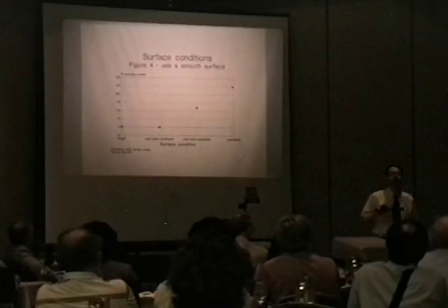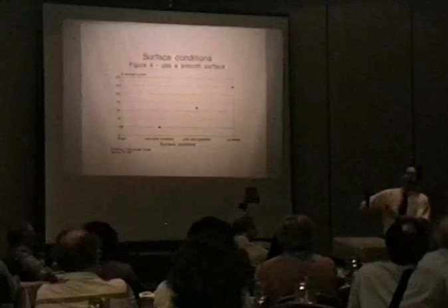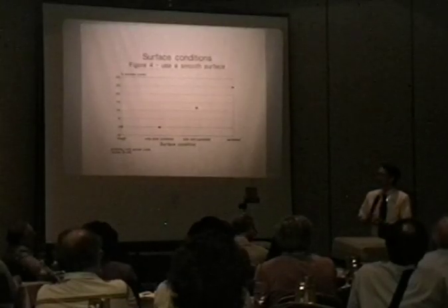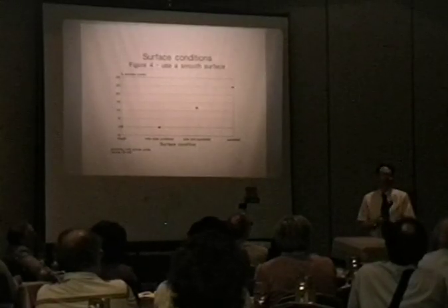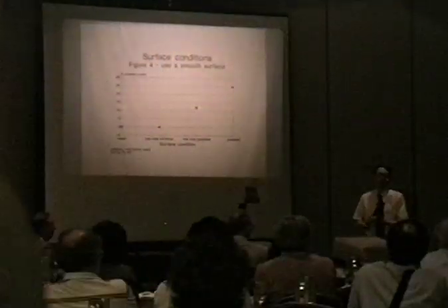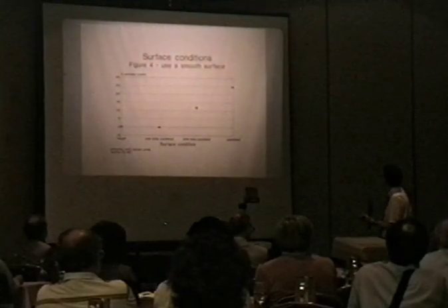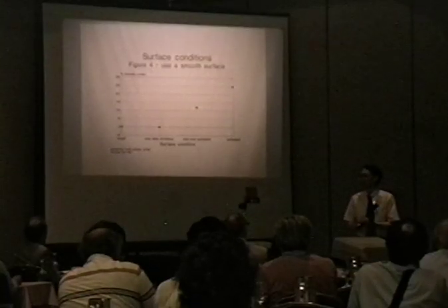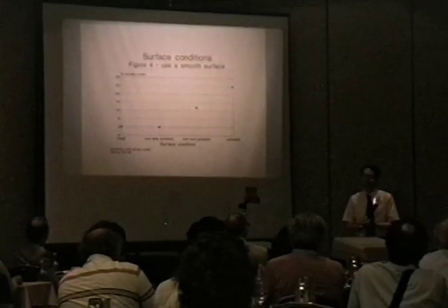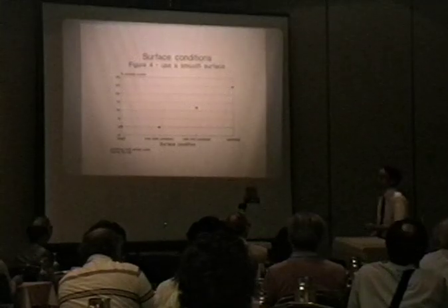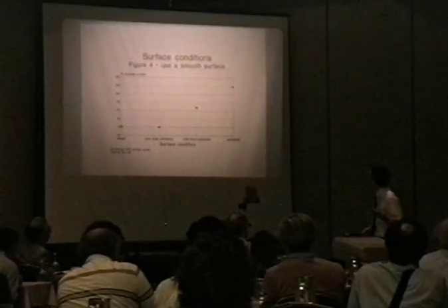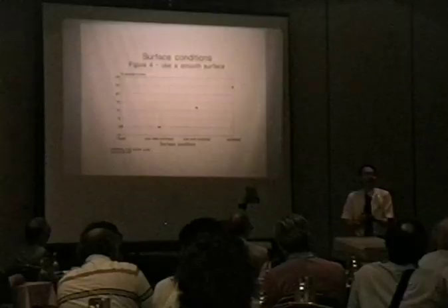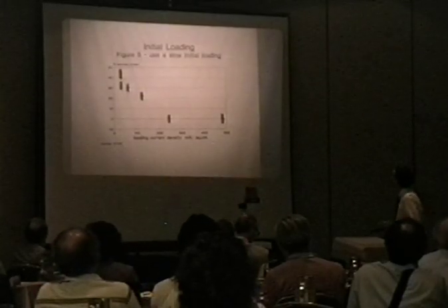I polish with a Black & Decker polish wheel, and then I take aluminum oxide, the kind that's used in chromatography, nice and fine. Then I polish it up. Then I finish it off on cotton with cerium oxide, the kind you use in optical grinding. The cerium may be important in some people's lives. Anyway, the cerium oxide makes a nice polish to it, is what I would say.